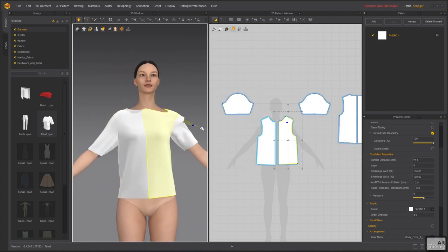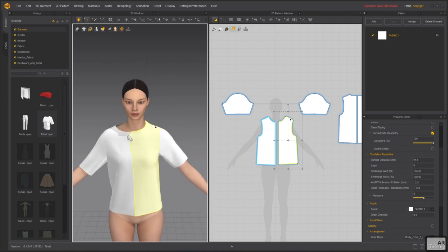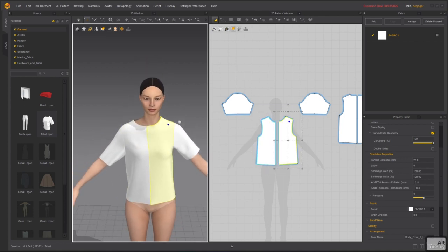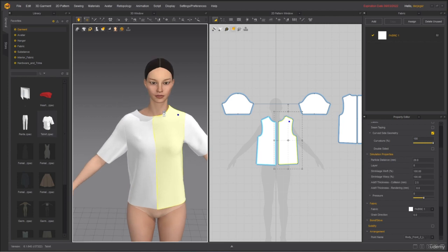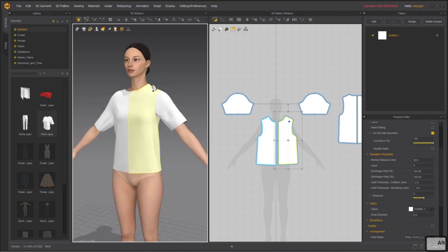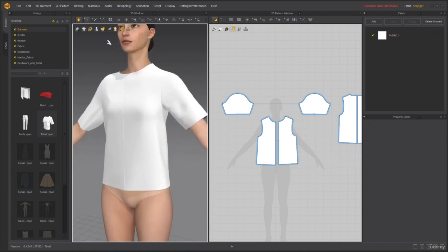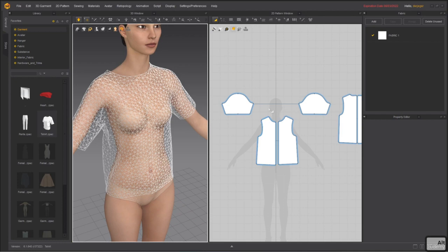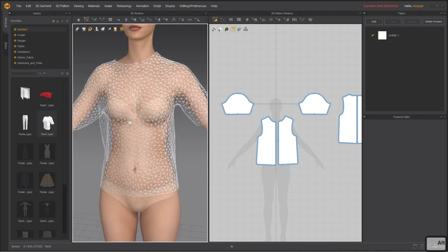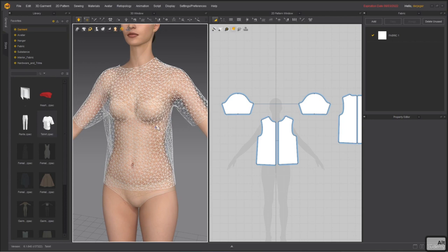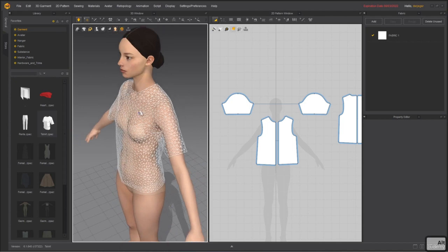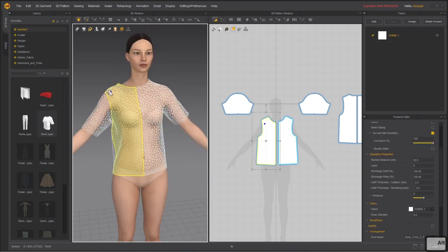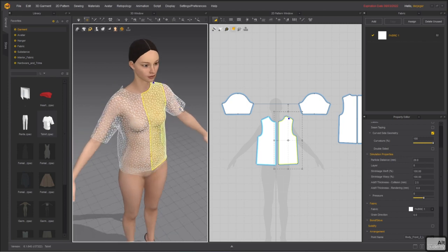So how does this work? Well, the way Marvelous Designer works, by the way, there's another sister program called CLO 3D, which is a little bit more geared towards people that are doing this for production, like for actual production of the garments in real life. In our case, this is perfect for VFX. And in both of the softwares, the way this works is by using this thing called the mesh. So the patterns that we create here get triangulated, very similar to the decimation process inside of ZBrush. They get triangulated, and those are the triangles that get simulated. The inner workings of the software simulate this thing to create the folds, the wrinkles, and all of the different things that we normally see here inside of Marvelous Designer.